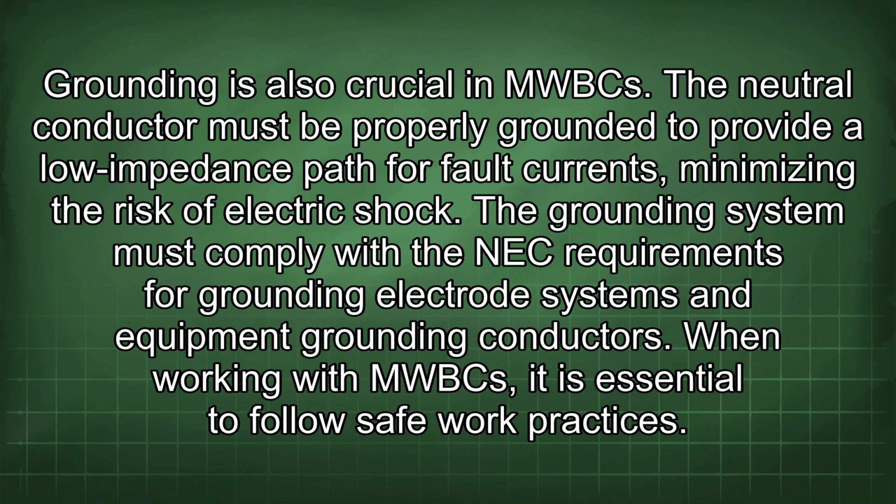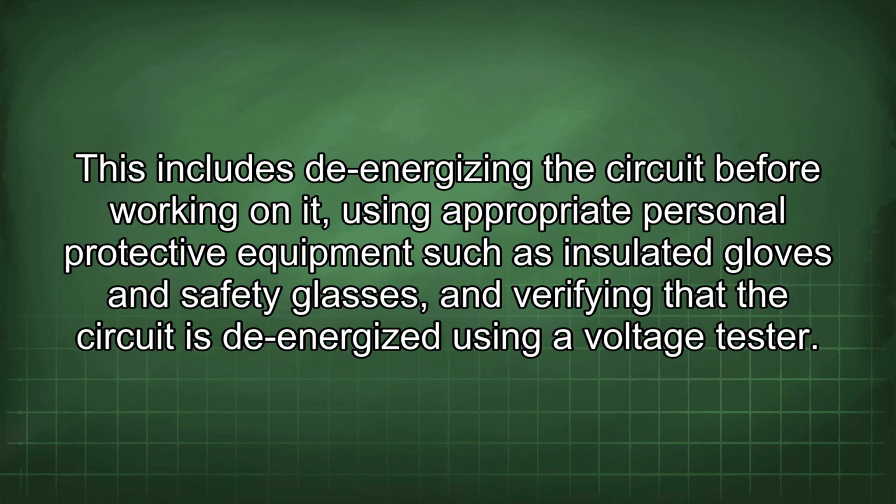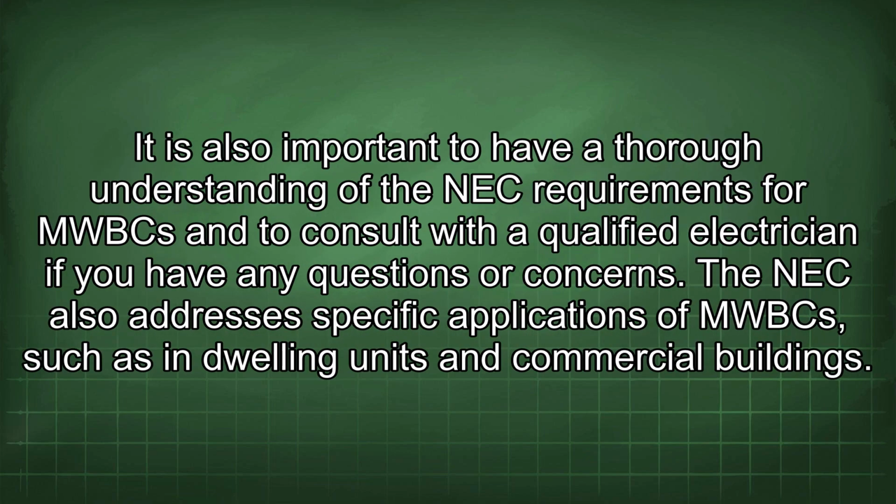When working with MWBCs, it is essential to follow safe work practices. This includes de-energizing the circuit before working on it, using appropriate personal protective equipment such as insulated gloves and safety glasses, and verifying that the circuit is de-energized using a voltage tester. It is also important to have a thorough understanding of the NEC requirements for MWBCs and to consult with a qualified electrician if you have any questions or concerns.